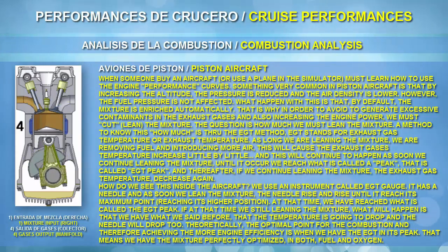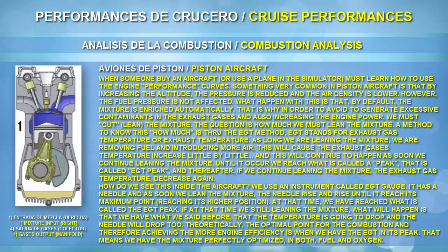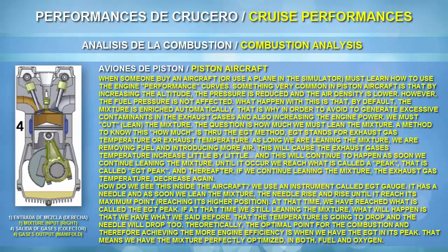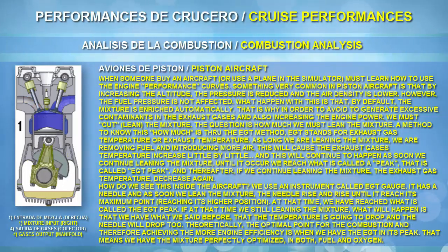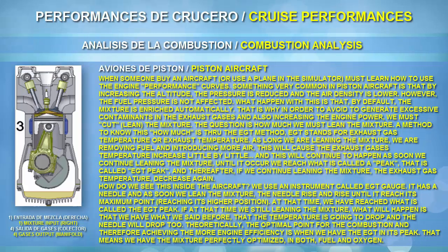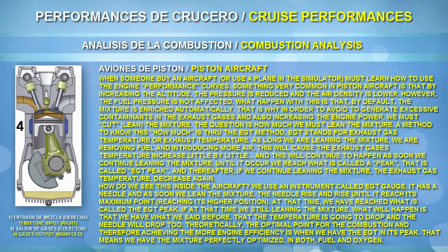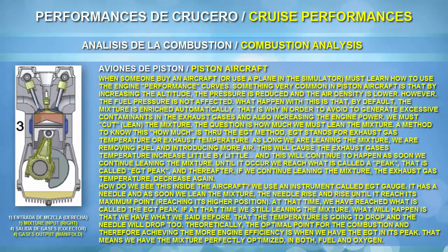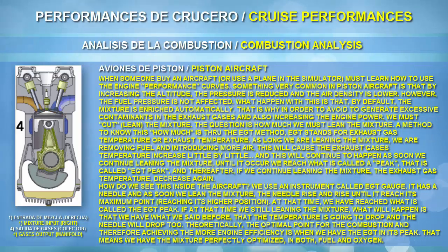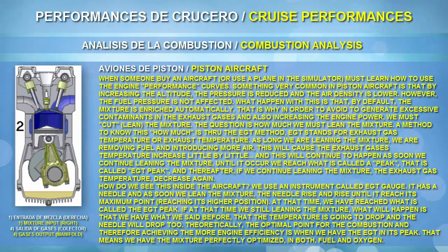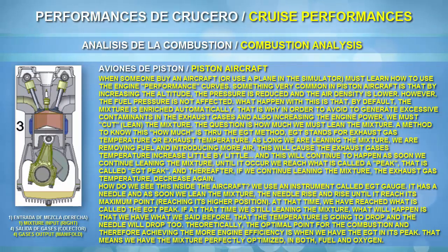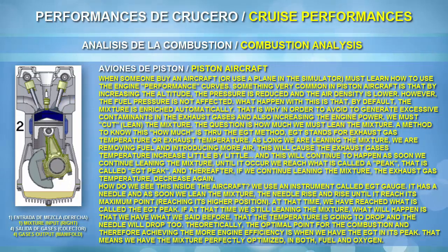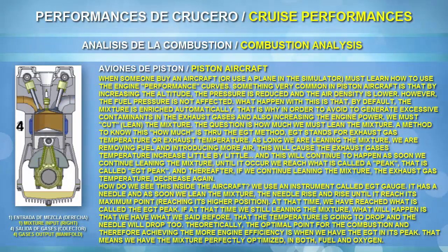and also to know what proportion of air and fuel we need to use, we need to calculate the EGT peak, okay? We will talk a lot about the EGT peak, but the idea is measuring the temperature of the exhaust pipe gases, to know they are burning at the maximum point, the highest point of heat, to understand that our engine is burning the fuel as it should, okay?